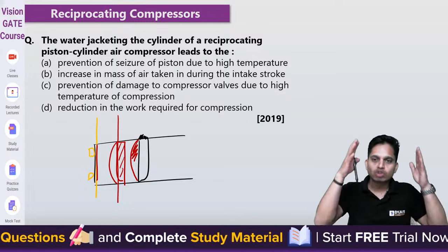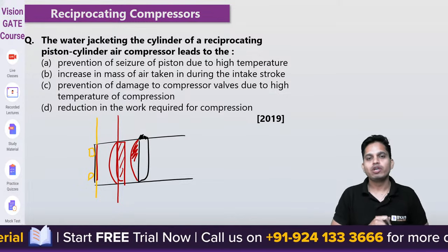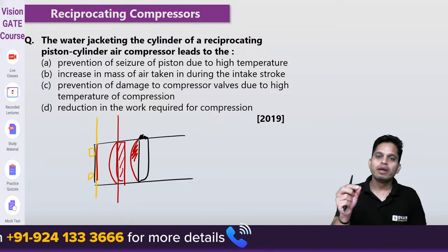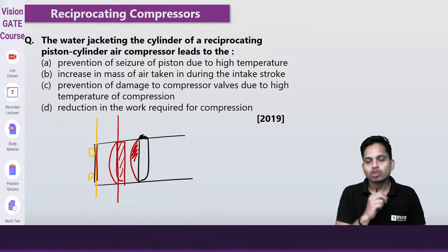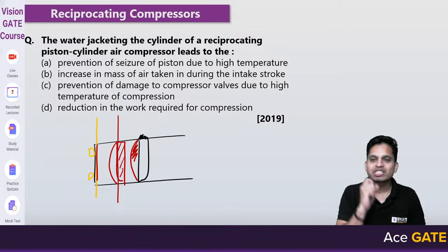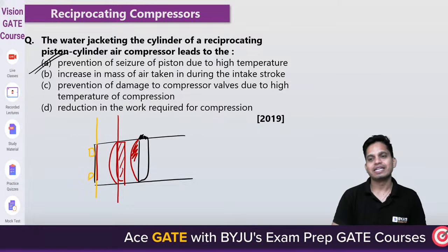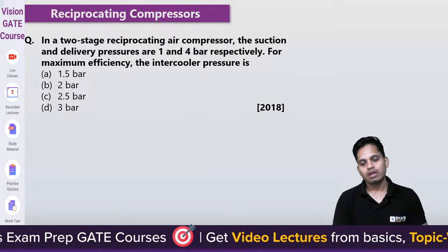So that's why you also apply a water jacket. The water jacket is to maintain a design temperature in the cylinder, so that the piston will not have high thermal expansion and it will not stop moving. Okay, so A is the answer. Chalo.